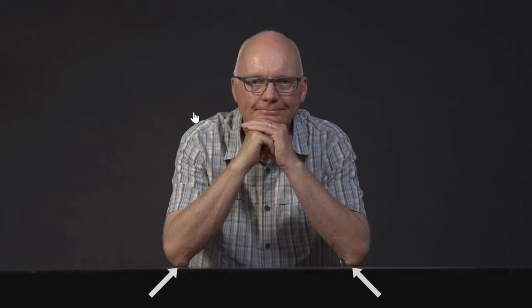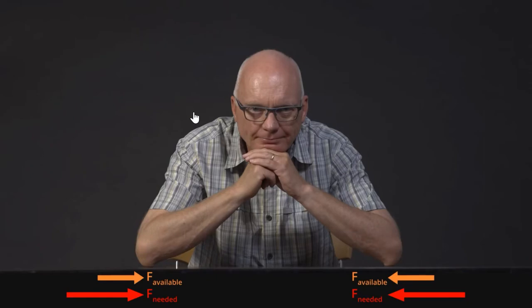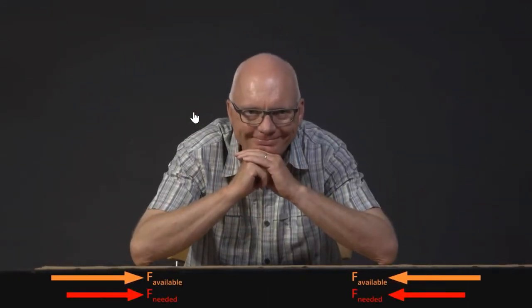You'll notice that these forces change depending on the position of your elbows. When your elbows are closer together, the forces become more vertical and their horizontal components become smaller. However, if you move your elbows further apart, you will discover that the horizontal forces increase. In doing these tests, it is important that you not use the muscles in your arm to stop your elbows from moving outwards. If you spread your elbows wide enough, the horizontal forces needed to support your elbows can become greater than the available friction forces, and your model arch collapses. Adding a rubber mat can increase the friction forces available at your elbows and thereby prevent collapse.